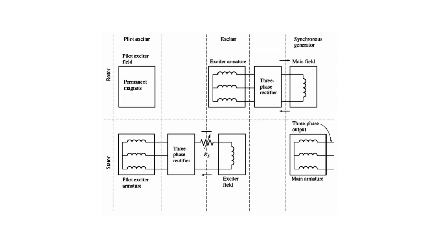So this is all about the constructional details of synchronous machines. As far as the stator of the synchronous machine is concerned, it is somewhat similar, having slots and teeth carrying the armature windings in this case. So in the next session, we'll start with the principle of operation of synchronous generators.